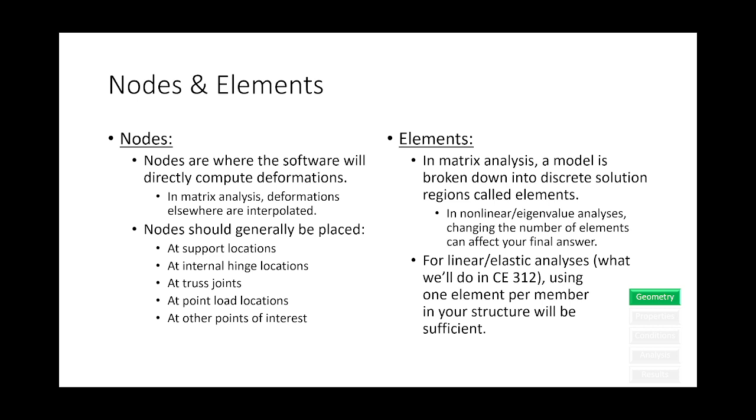All right, let's talk about what nodes and elements are. We are using a matrix stiffness analysis process that's really a specialized approach of what's called finite elements. Have any of you ever heard of finite element analysis? I think maybe some of you have. I'm not turning this into a graduate course, but finite element analysis is basically a means of taking a bunch of differential equations and turning them into linear equations. That's kind of what finite element analysis is in a nutshell.